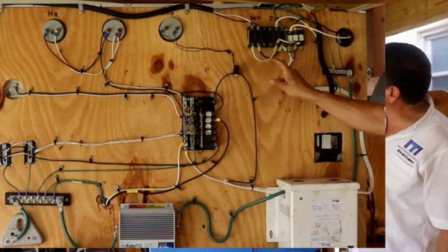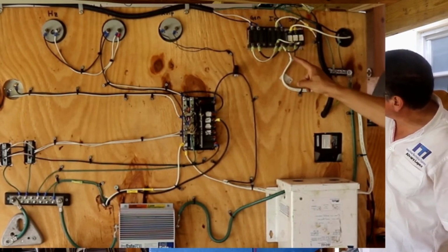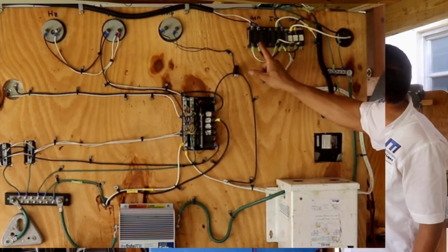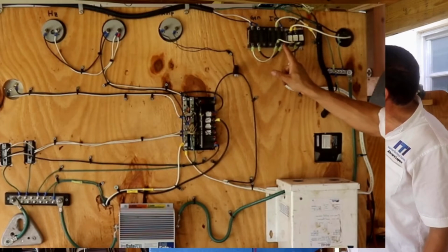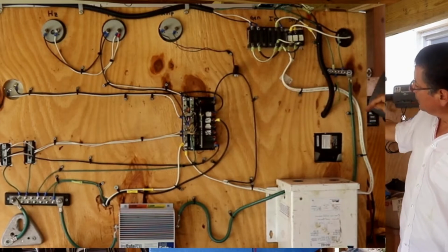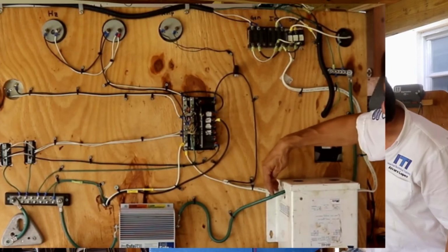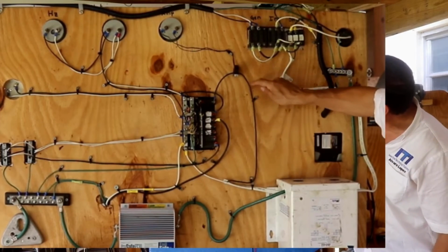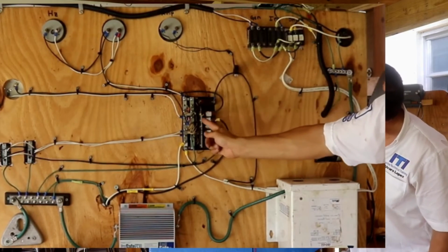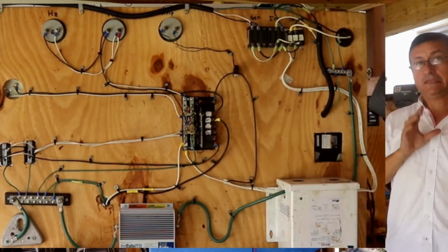Okay, the outputs should be connected together. Neutral of the generator connected with the neutral of the inverter and connected with the neutral of the shore power, and from that connection is the neutral of the output. Okay, the hot line of the generator is connected with the hot line of the inverter and the hot line of the shore power, and from that common point, this is the output power passing through the isolator transformer, and this is the output of the isolator transformer, hot, entering the main breaker. This is the output of the main breaker entering into the hot bus bar, and those are the outputs of each individual breaker. That's clear?